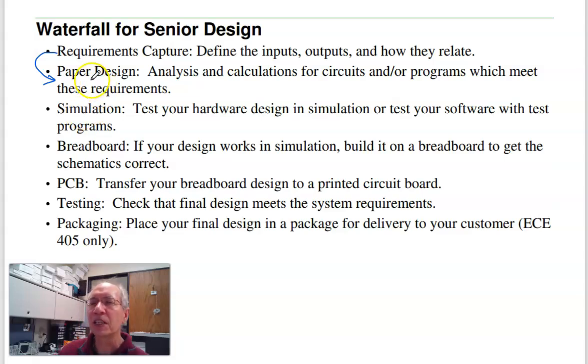Once I get a paper design, I'm going to check my design. It works on paper. Does it work in practice? First step is to simulate it. That's using Circuit Lab. I can check my design to make sure it works. If it doesn't work, I can modify it in Circuit Lab until it does work. Currents are within 20 milliamps. Transistors are saturated.